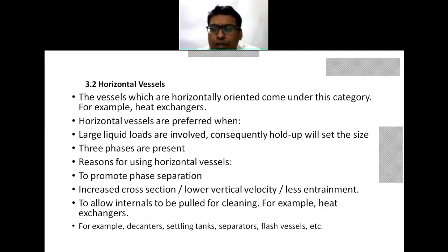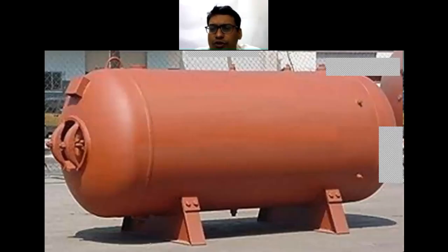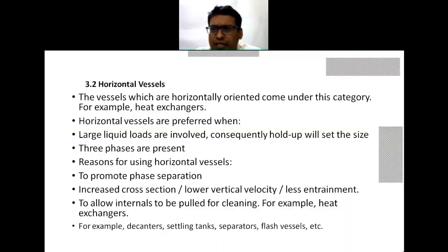Then the horizontal vessels. Their orientation is only horizontal, and they are mostly cylindrical vessels. Vessels which are horizontally oriented come under this category. These horizontal vessels are preferred when large liquid loads are involved, because we have to handle a large quantity of liquid.